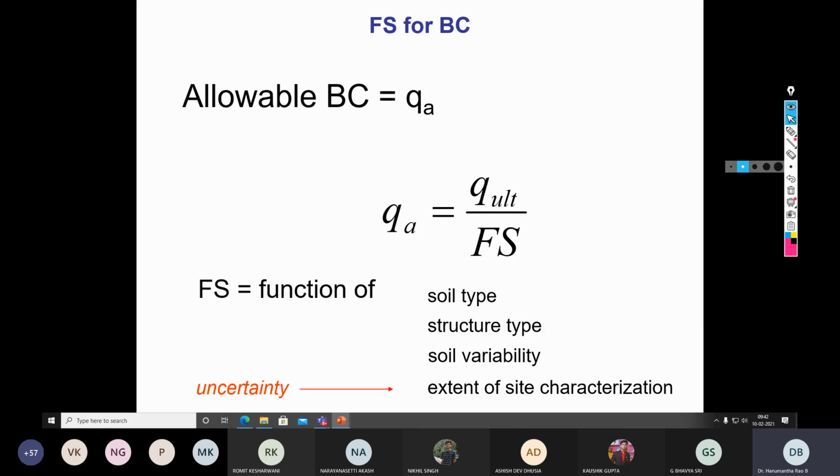So for example, we talked about a couple of terminologies, ultimate bearing capacity. Then there is another term called allowable bearing capacity. The ultimate and allowable, let me explain to you. Ultimate means it is the maximum amount of load the soil is able to bear. Now when I say the maximum, the moment I apply the ultimate load, the soil undergoes shear failure. That's for sure. But when I say the allowable, Q allowable, what is that allowable? Here the allowable is the settlement. Allowable is settlement.